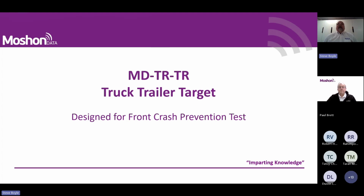We looked at IIHS, and they were testing forward collision warning system notifications by driving at a real truck trailer, a dry van trailer, a very common trailer in America, and recording when the forward collision warning was activated. If it activated, they would swerve around the vehicle. If it didn't activate by a certain point in time, it was deemed a fail. So we talked to IIHS about designing a target and what they would want from it.